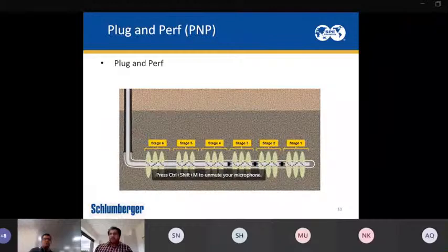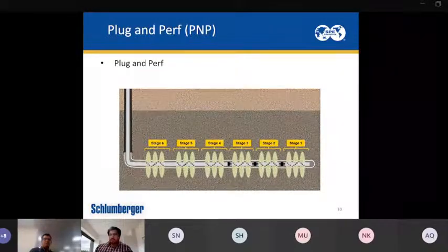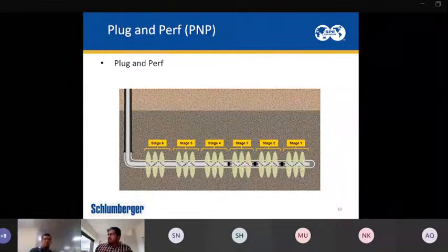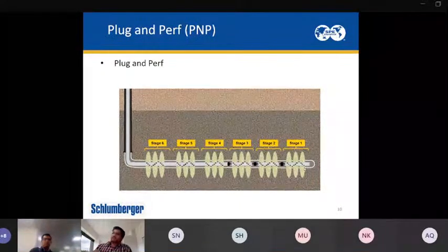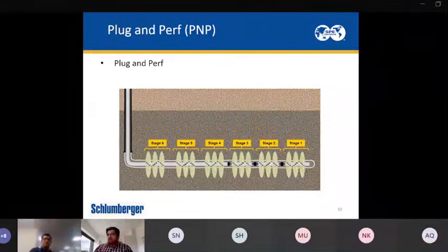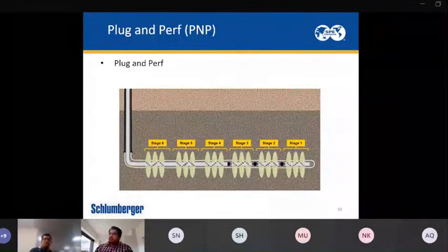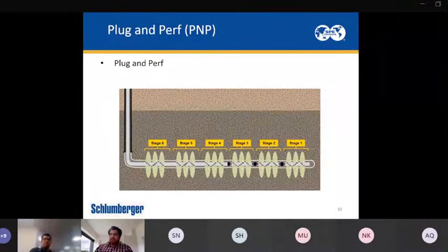So let's consider a horizontal well which is ready to be completed. It's a cased hole cemented well. Once the cement is done, we will wait on the cement to make sure that it's hardened. Once it's done, we can move the rig. We can perform this hydraulic fracturing operation rigless. Basically, once the well is cemented, we don't have any access.